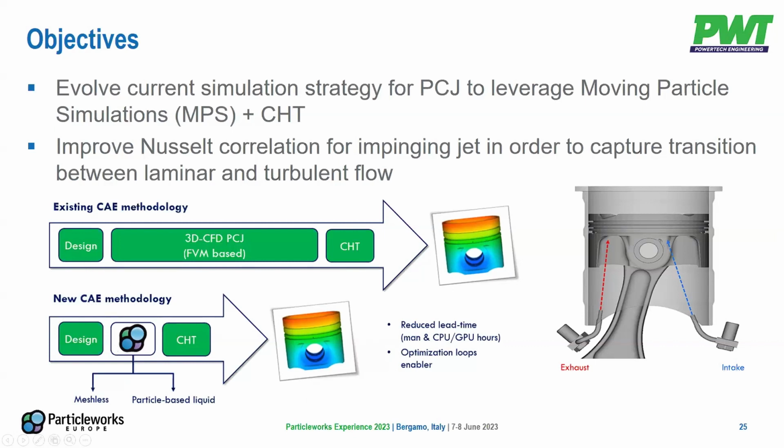So the idea here was to understand how well the method could compare to the previously held workflow, the existing methodology, and also to finely tune, in this case, the piston cooling type of correlation to predict HTC.